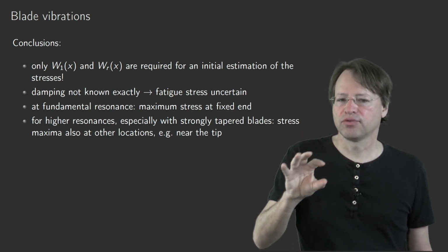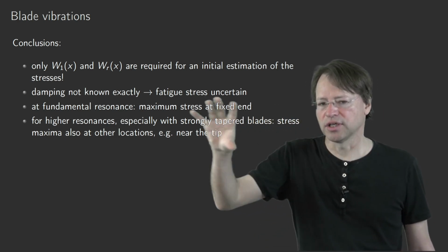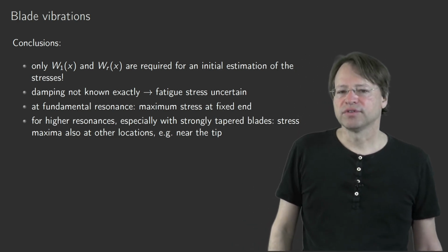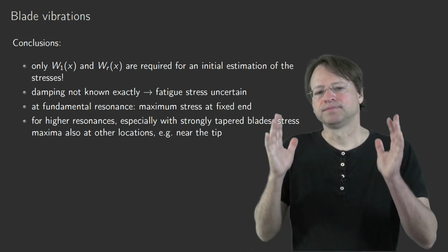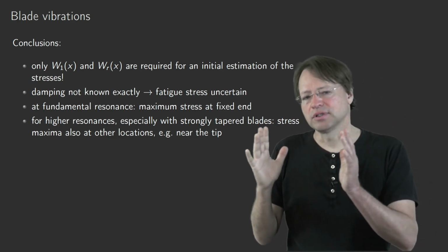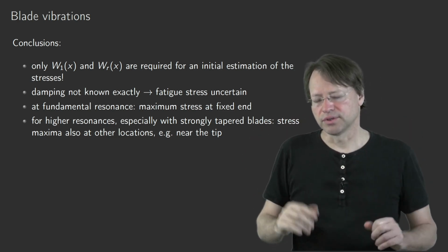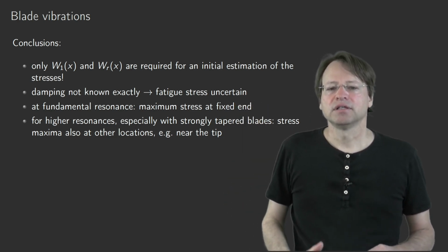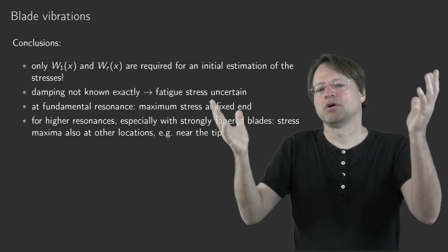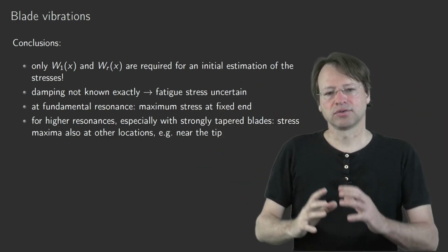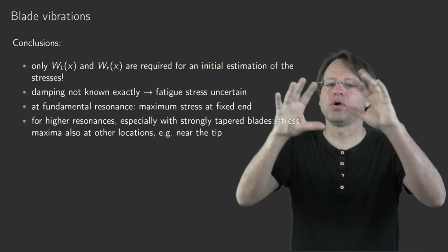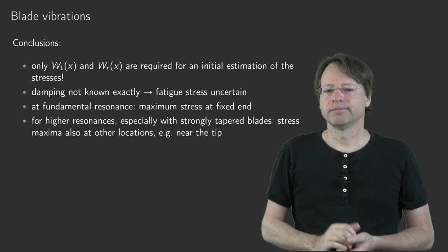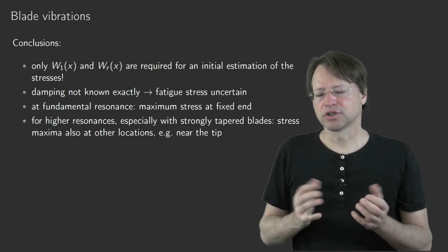rotor that is perfectly symmetric in order to have that stationary field. And in practice, this is not the case. So what you will find in practice is that there are disturbances of that perfect symmetry of your rotor with respect to the structure of these blades. And this leads, so you have global modes of the whole structure. So considering the rotor and all the blades as one structure. So think of a finite element approximation you would do of that whole structure.